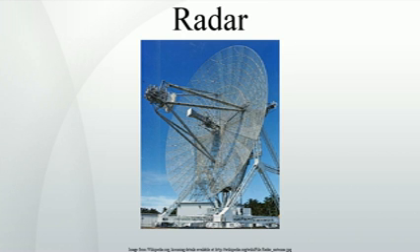Transit time. One way to obtain a distance measurement is based on the time of flight: transmit a short pulse of radio signal, electromagnetic radiation, and measure the time it takes for the reflection to return. The distance is 1/2 the product of the round-trip time, because the signal has to travel to the target and then back to the receiver, and the speed of the signal.